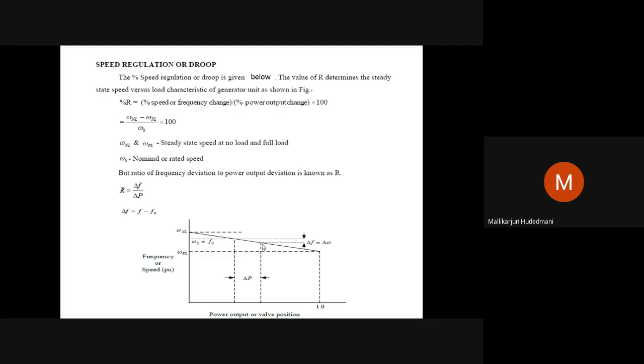That is known as deviation in the frequency. That frequency deviation can be calculated as the difference in omega or F this way. You can see here F minus F naught. What is the frequency prevailing right now on the incremental load? What was originally F naught? F minus F naught gives you the deviation. That is the drop in frequency from the original operating point, and the shift of power or load drops the frequency, and this change is known as frequency deviation.